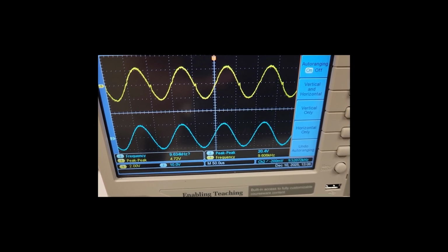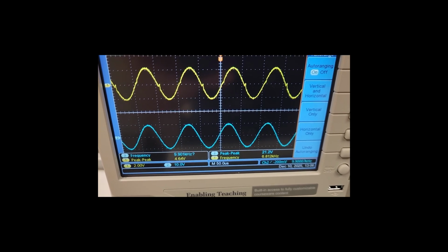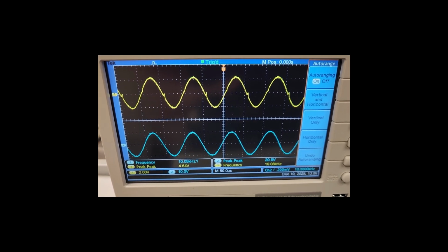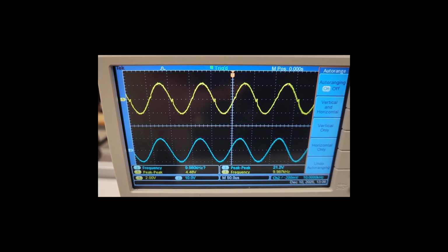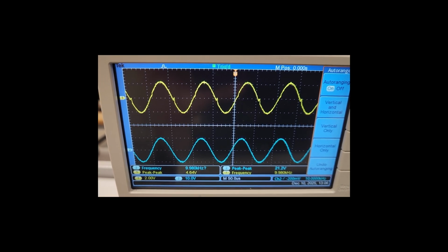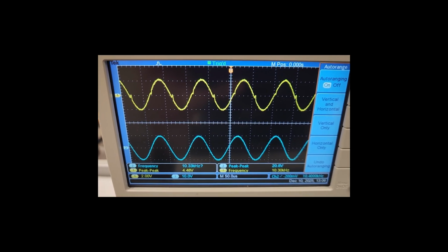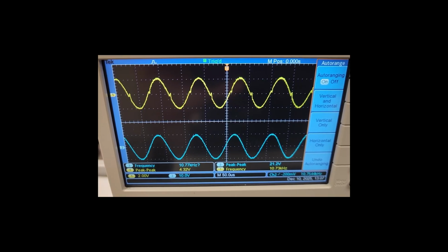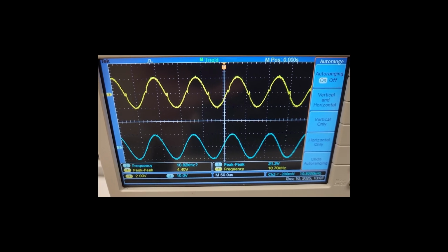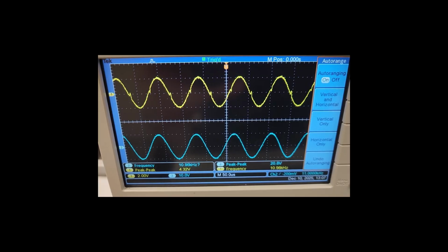and now we're at 10, you see how it's increasing slowly? That's because this op amp's slew rate has limitations starting around 10 kilohertz, and if we go past this, you're going to see that increase rapidly. Also, you're going to see a decrease in the peak-to-peak gain.